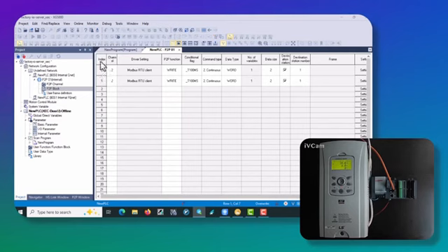Now I choose my channel, which was channel 2, Modbus RTU client. I select the P2P function as write, right? Because I'm going to perform a write operation and send the frequency value to the inverter, and I'll also send the start command over the network. For the inverter, I set the conditional flag to 100 milliseconds. My command type is continuous and the data type is, since the values I'm going to send to the inverter are of integer type, I set it to word.